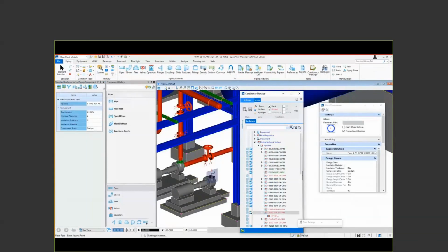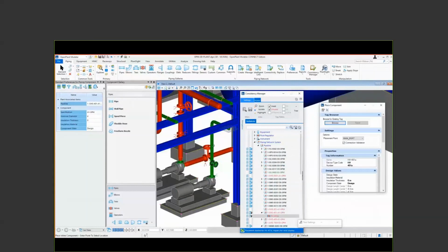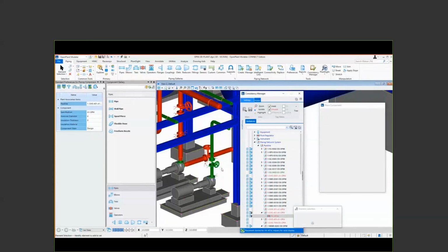So first we'll model some piping in. The piping tool has all the automated routines for auto inserting flanges and elbows at intersections and T's and whatnot as you're modeling. And next I'll right click on the gate valve that I want to insert from the PID. So in this case, that's the gate valve. It'll take on the tag HV401A, orient the hand wheel.